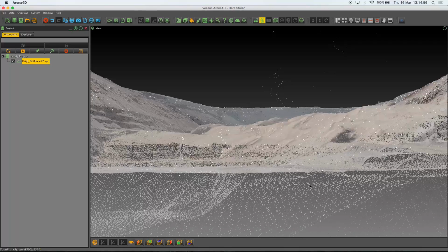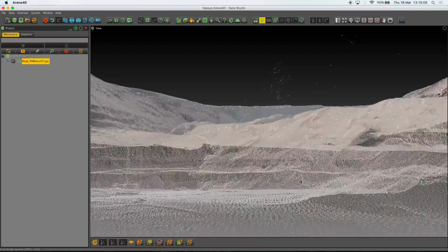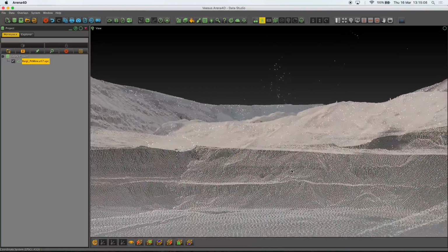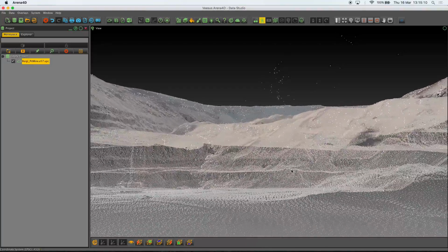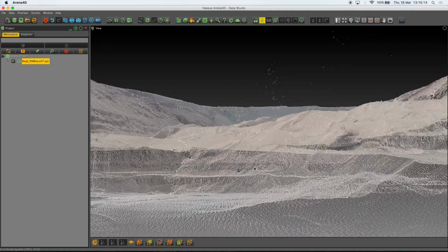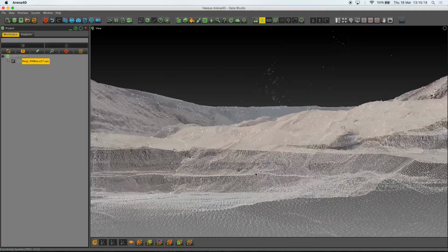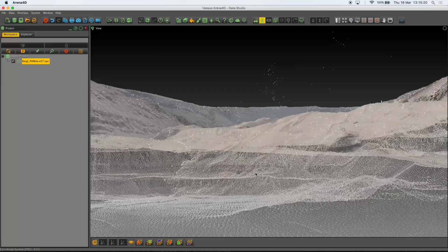I mean, you can see they're quite slow in this context, but if you were walking down the street, you wouldn't want it to be too fast. But if I hold the Shift key down and now hit the W key to walk forward, you can see it's a lot faster. It's increased my speed. And it'll do the same thing for the S, A, and D keys. But it also does the same thing for the scroll wheel. So I'm holding Shift down and I'm using the scroll wheel to lift myself up a lot quicker.